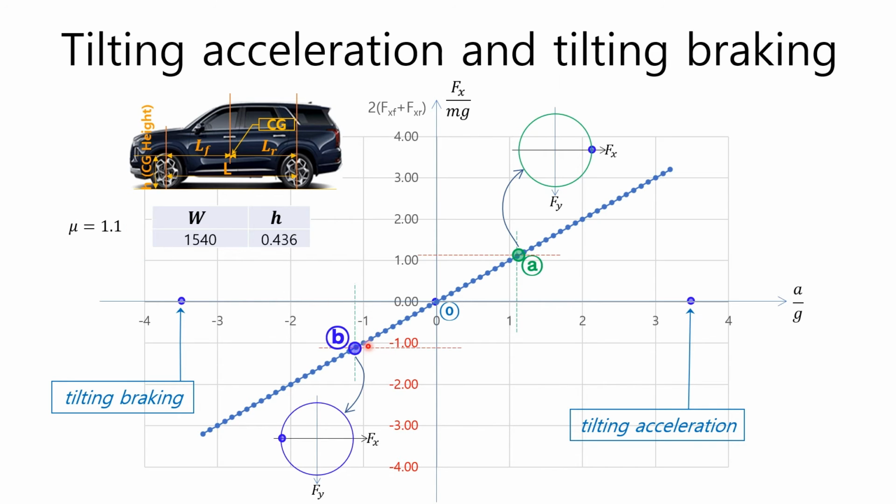friction force for braking at driving state B and the rear tires use up all the friction force for traction at driving state A. Therefore, when the force due to the braking torque exceeds B, sliding occurs on the front wheels, and when the force caused by the engine torque exceeds A, spin occurs on the rear wheels in the case of the rear-wheel drive vehicle.